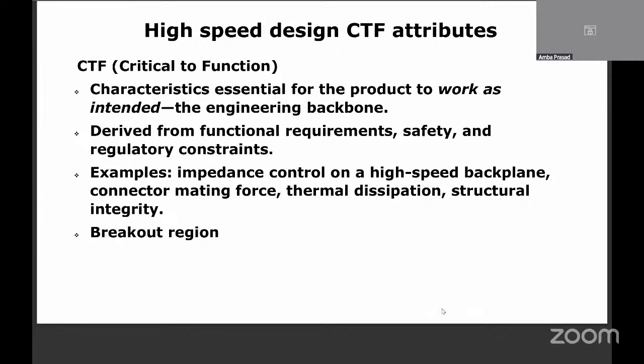They check the schematic also, the safety part of it, regulatory part of it. They check the schematic, they check the layout, and they check the live board also. So then what we projected in pre-layout or pre-manufacturing, there can be a few dBs of leakage. So that has to be fixed. We may have to go for a second rev.